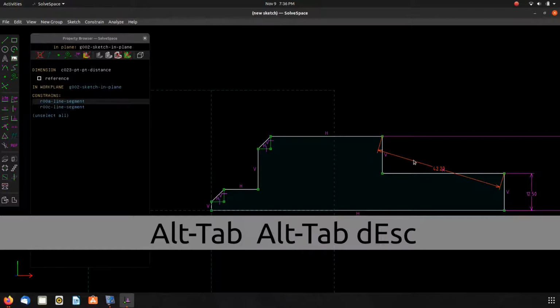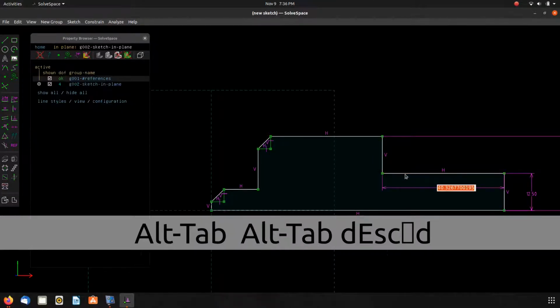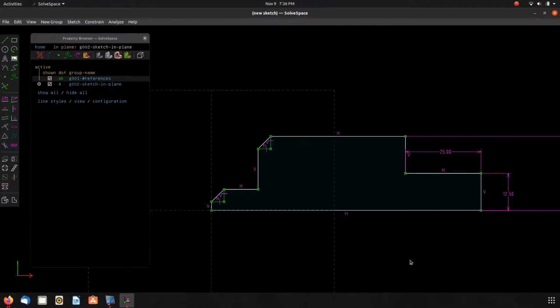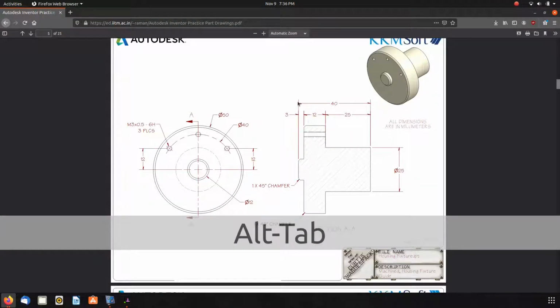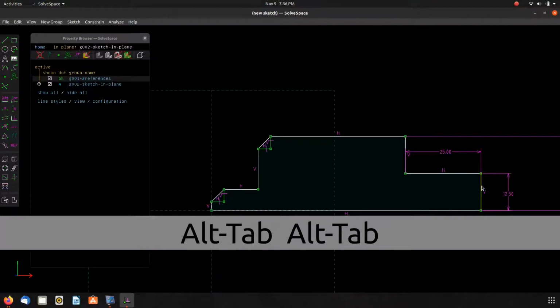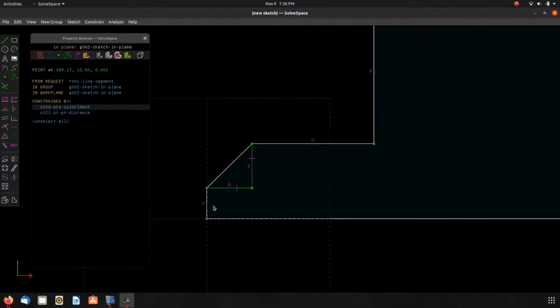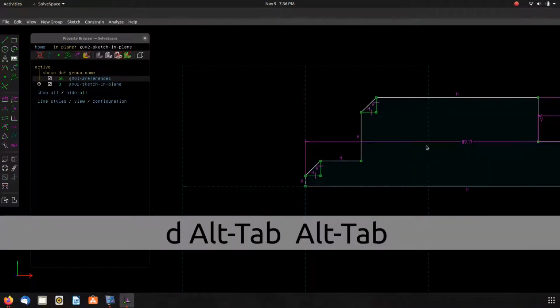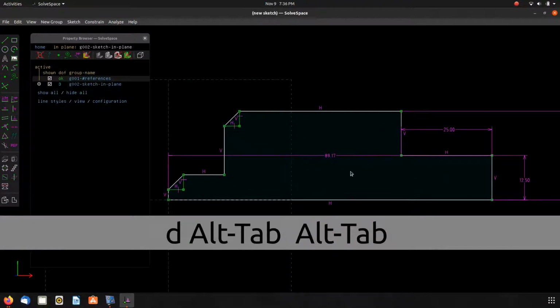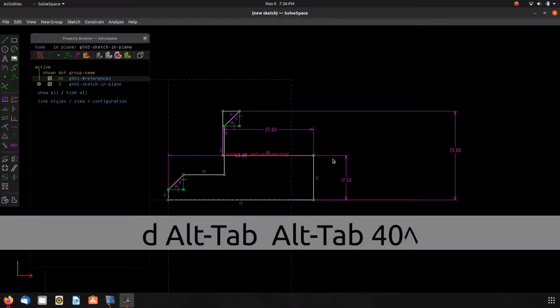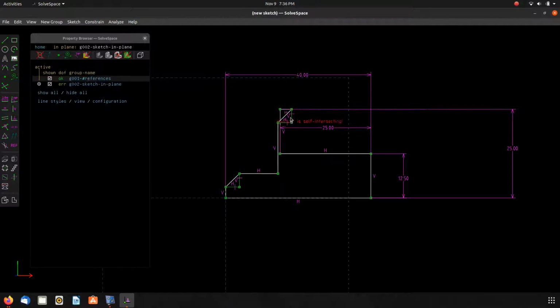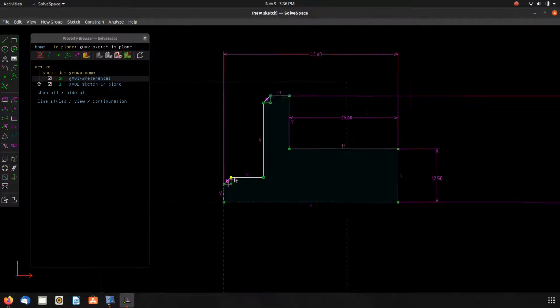that is not what I wanted, not the distance between the two, but rather that distance there is 25. And for the total distance front to back, you can select that point and this line segment here, and that will be a total distance of 40 millimeters. And again, no auto scaling, so it broke the sketch, but that's okay. We can just drag it to where it looks okay and keep going.